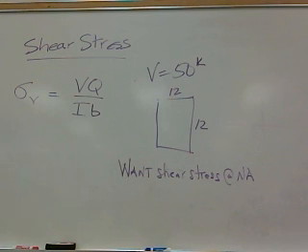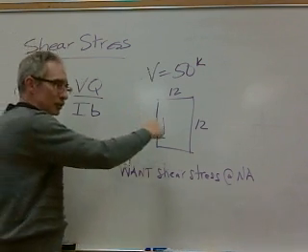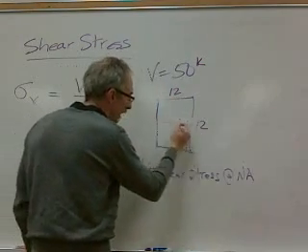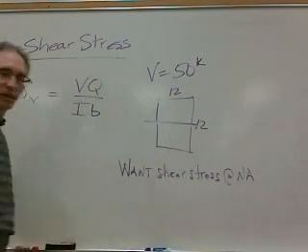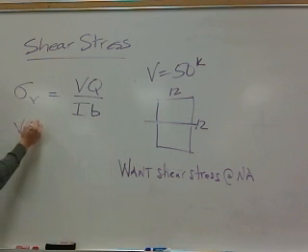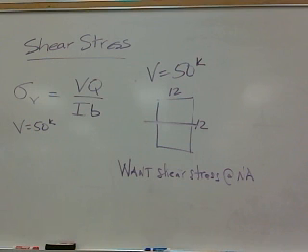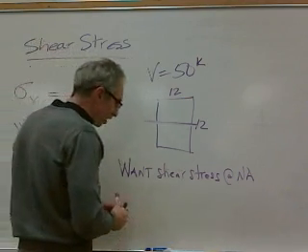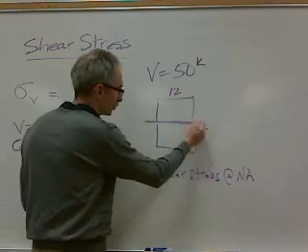Now, again, you're going to be doing problems where you have to actually find what the shear force is, or maximum shear force. Your beam is just a 12 by 12 square. Neutral axis, of course, is at the centroid in the middle of that shape. Okay, so what are you going to do to calculate the shear stress? What I do is I simply go through and list the four components. V, okay, Q, and here's the way Q works. I want shear stress at the neutral axis.